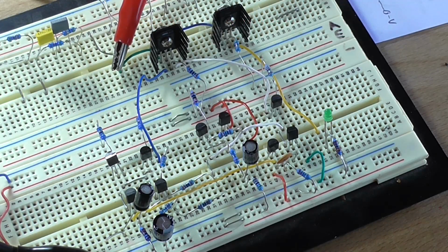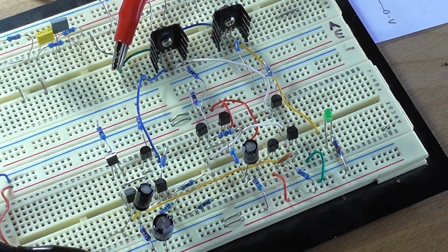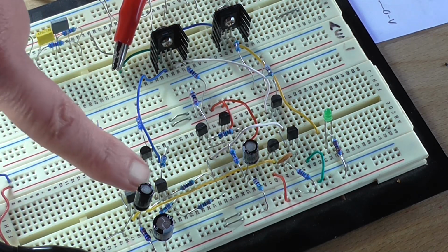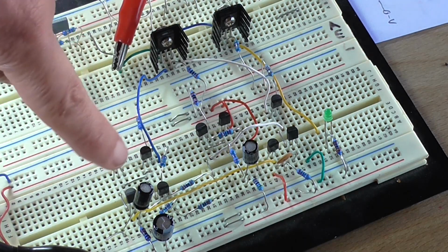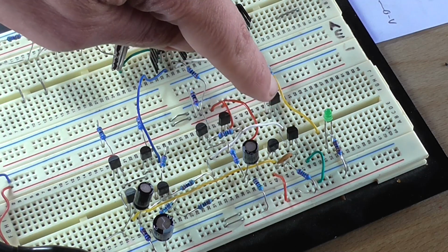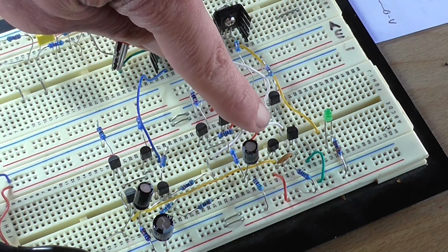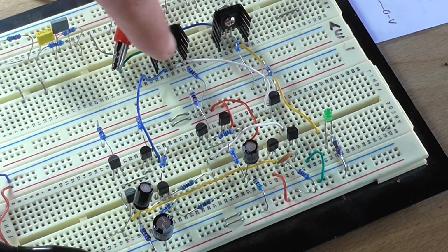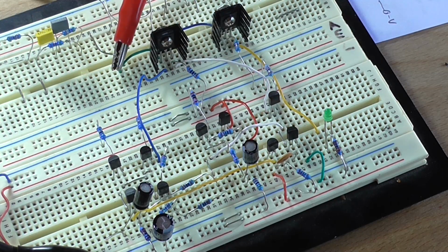Alrighty then, about an hour later, or close to it, yeah, about an hour, I've got the circuit fleshed out. So down here, these two transistors here are the long tail pair. These two transistors here are the current mirror. These three transistors here are the current source transistors. These two transistors down here are the bass. There's our voltage reference LED. It measures at about 1.8 volts, not 2.1.